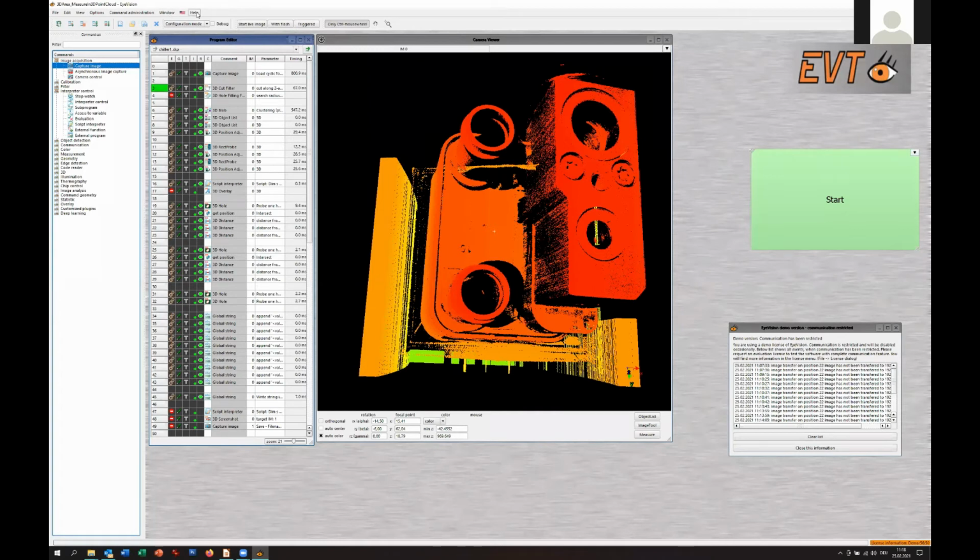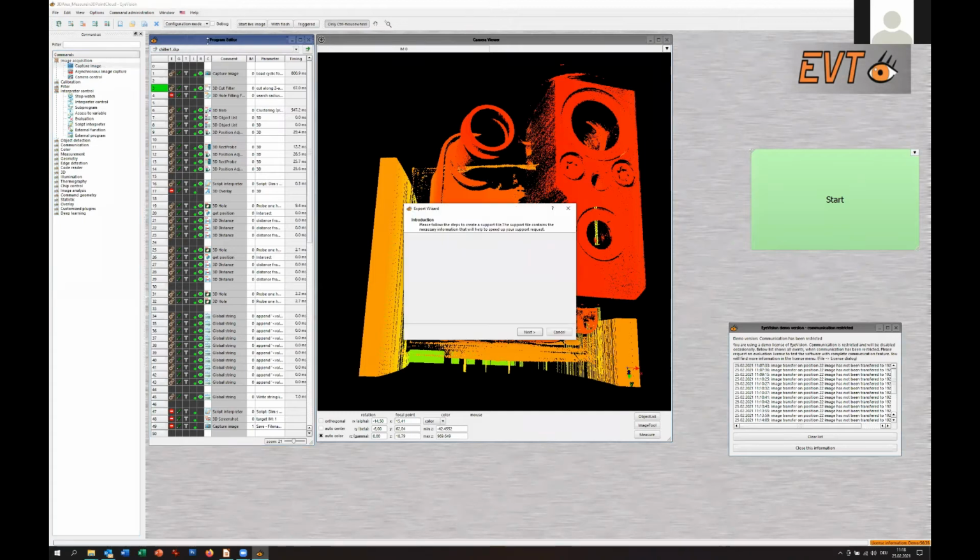Another thing, so for example, if you have problems sometimes, and we see it always also with the camera, maybe with the drivers or whatever, we have this support file. This is also very helpful, and I recommend it if you have a problem and you say, okay, I set everything up, but the camera is not working or whatever. You should use this create support file.